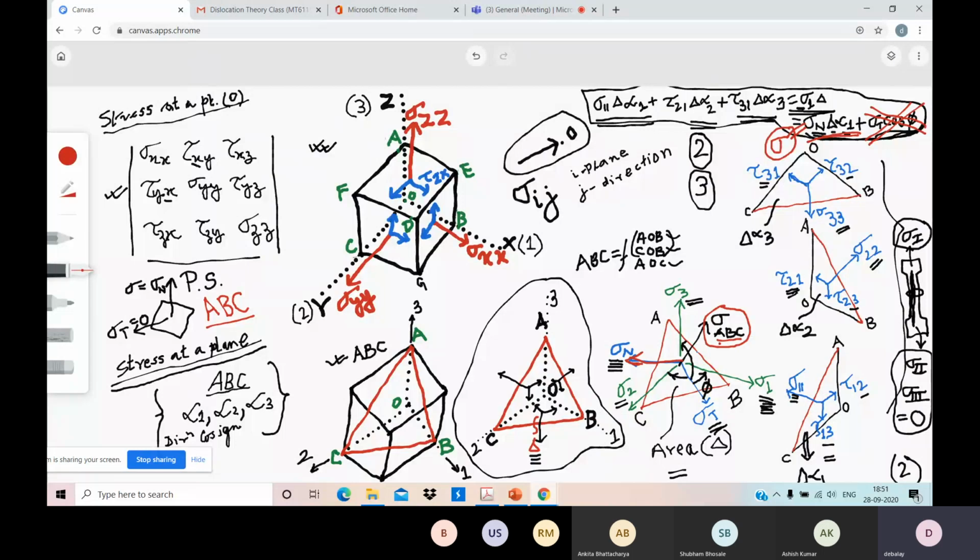Since in the generalized case I had a shear stress and a normal stress on that plane, I showed the net resultant in a different way so that you can divide it into normal component and shear component. But if there is no shear component, then the net stress will be basically your normal stress. So you can write sigma n, or the net stress sigma, as basically the same, and that is acting perpendicularly.